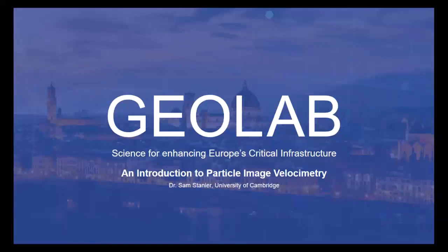I suspect what they're doing is surveying. So they're probably taking pictures from multiple viewpoints and then using structure from motion to get the topology of the seabed around whatever object they're looking at. The big challenge in that sort of environment is you're not in control of the image texture. The seabed is what it is. You can't go and pepper it with modeling flock or dyed black sand. I mean, you could, but no one's going to do it. So you're always limited by how much natural texture there is on the seabed, wherever you're operating.